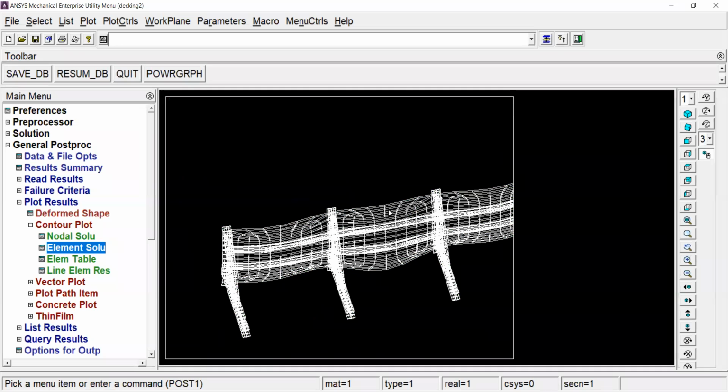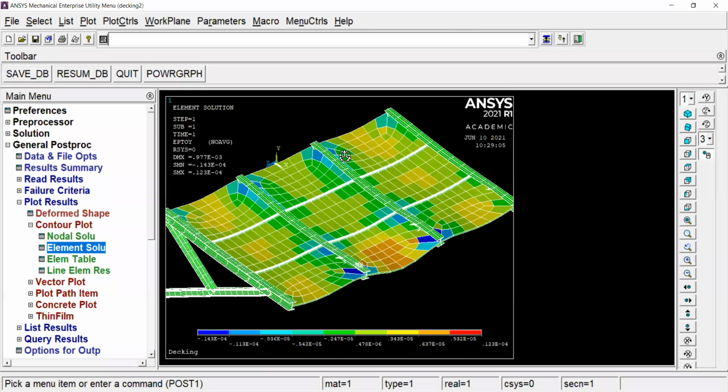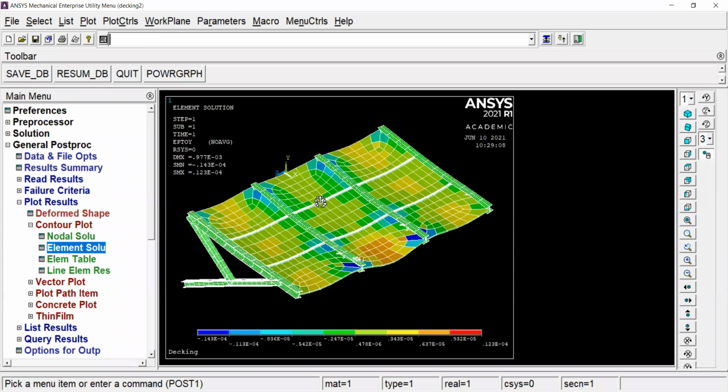But I want to remind you that just doing this one time isn't enough, okay? So we've done it once and we found that using these sectional beams, and the sizes that we have, we've way over designed this model. So if you were to go back, we could change some of the sectional properties, apply different sections, simply change the material section and then solve it again and see if we can use less material and get a better factor of safety.